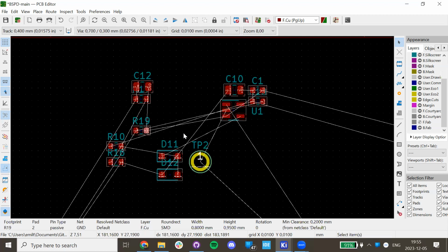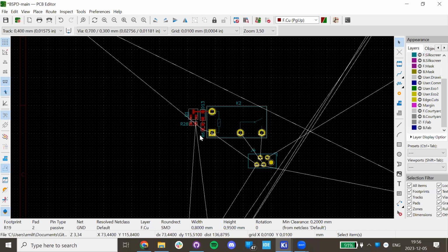Now I will add something that we learned as well. If you have copper on one side instead of the other, across the whole layers, it should be as symmetric as possible. Otherwise, if one layer, like the inner layers, is thicker, but the other one is not, I guess it can bend the whole structure. Yeah. All right. Now we learned that as well.